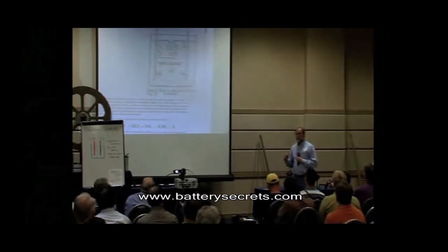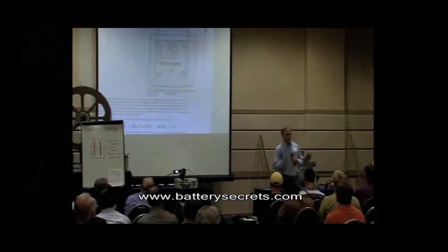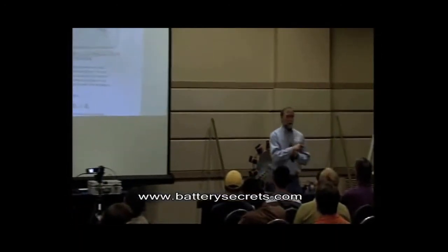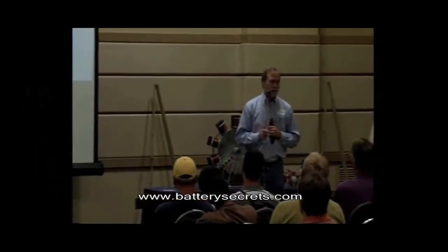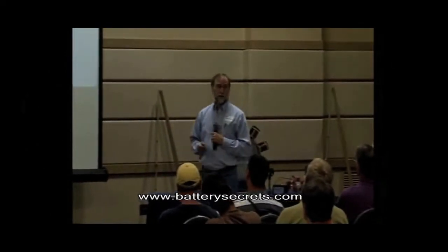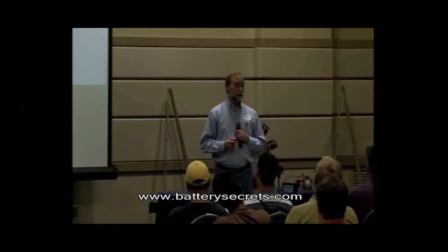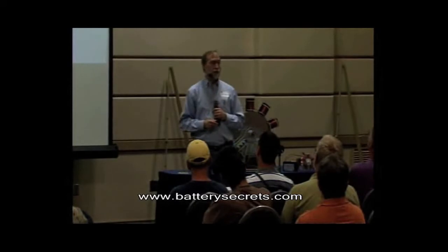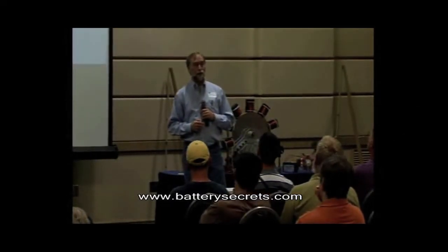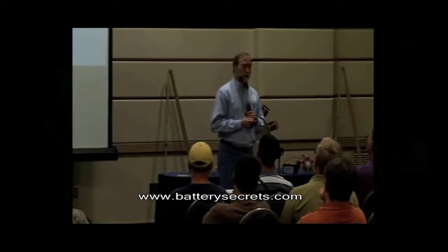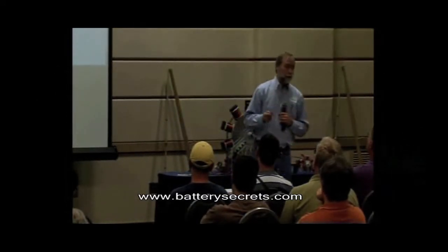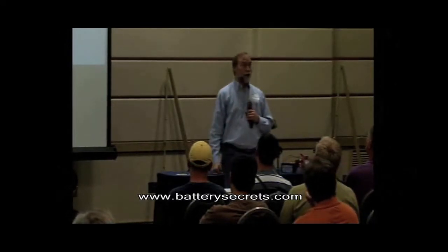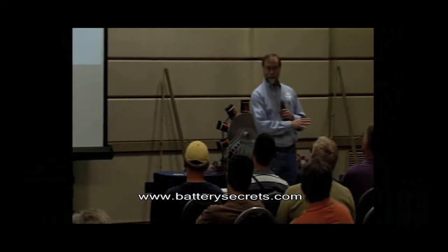And this isn't just, the big buzzword out there is pulse charging. But these chargers are not just pulse charging. They do use impulses. They do use these methodologies. But in a much more sophisticated way. Even the big pulse chargers out there will usually, especially when you get into the really big batteries, have a thermal sensor that you stick on the battery so that when the battery gets too hot, they shut off for a little while.